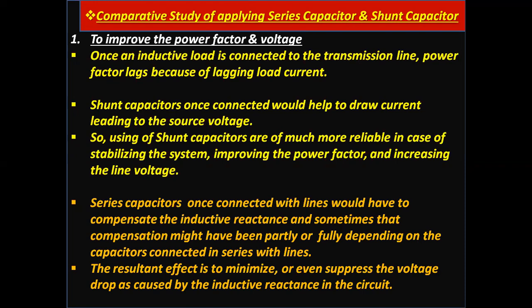Shunt capacitors, once connected, would help to draw current leading to the source voltage. So, using of shunt capacitors are of much more reliable in case of stabilizing the system, improving the power factor, and increasing the line voltage.